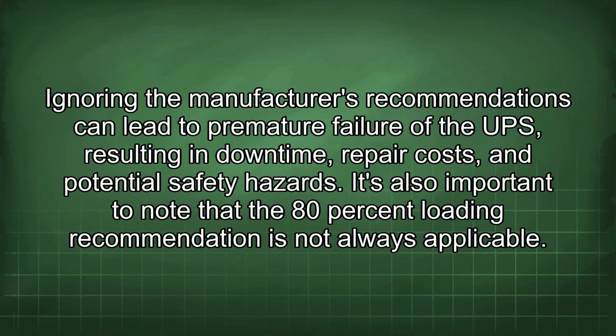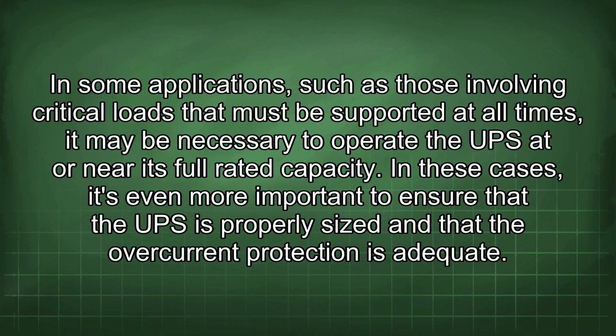Ignoring the manufacturer's recommendations can lead to premature failure of the UPS, resulting in downtime, repair costs, and potential safety hazards. It's also important to note that the 80% loading recommendation is not always applicable. In some applications, such as those involving critical loads that must be supported at all times, it may be necessary to operate the UPS at or near its full rated capacity.